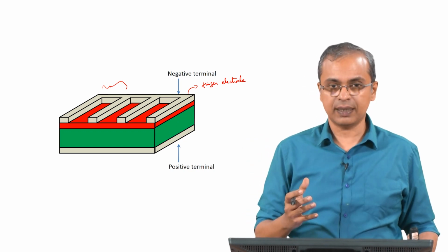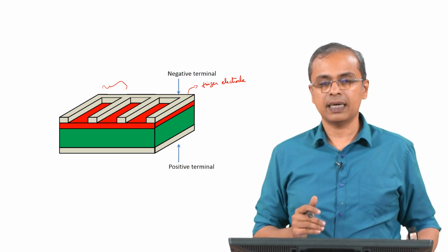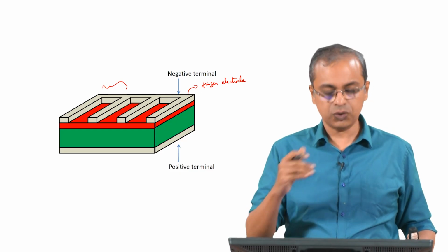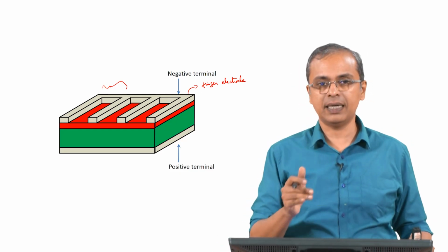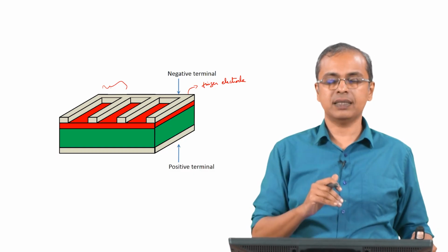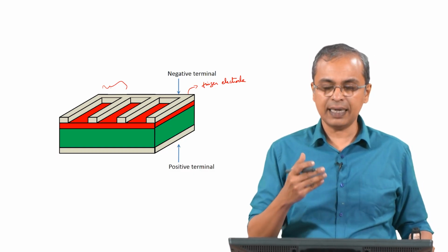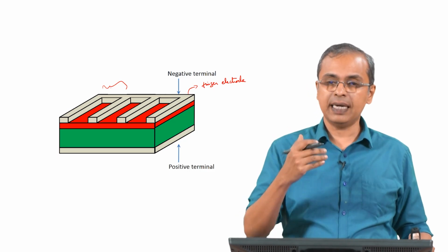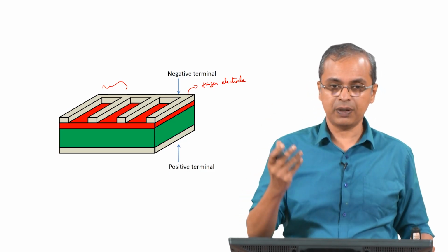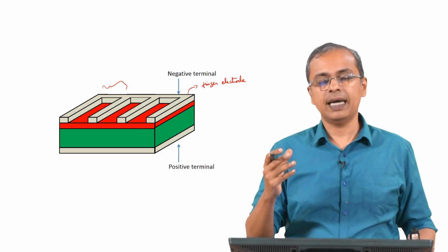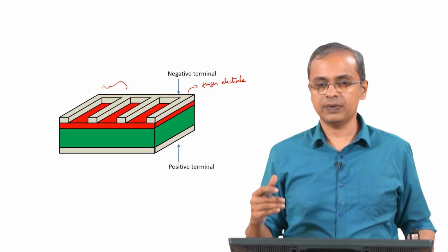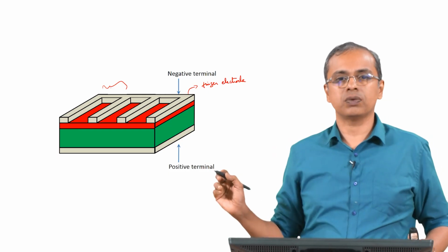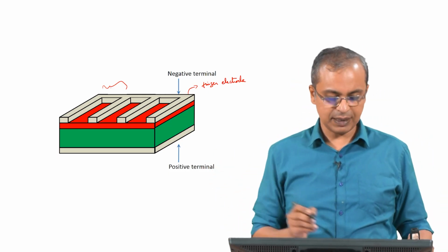And so that is how the system works. So you have sunlight coming through, past the finger electrodes, goes through, let us say in this case, the N material, the N layer which is thin, reaches the PN junction, and there generates the electron hole pair. The electrons get tapped through the top electrode, which then is the negative electrode, and the holes get tapped to the bottom electrode, which is the positive electrode. So this is your circuit. This is the basic structure that you use.